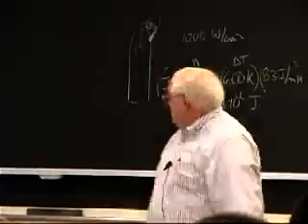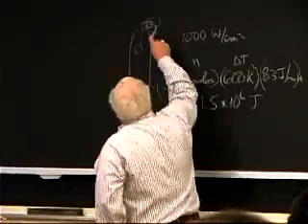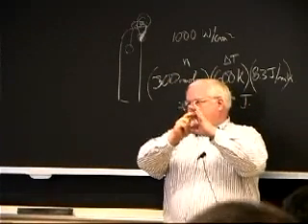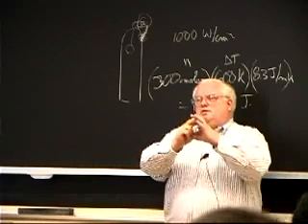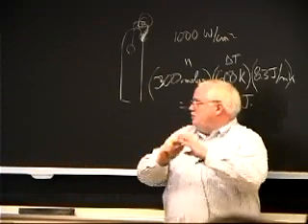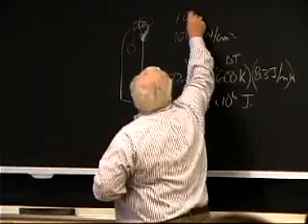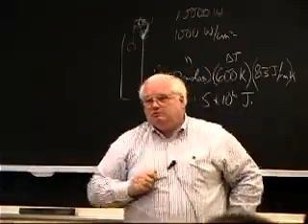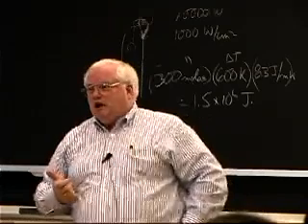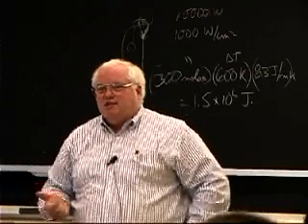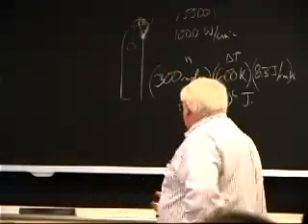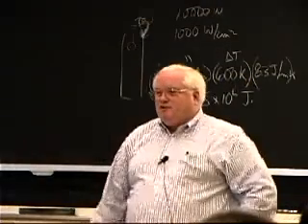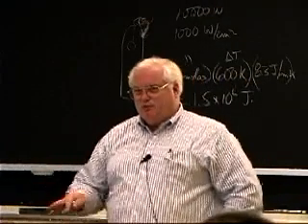Okay, and let's say I have a big flame here. It's not just one square centimeter. Let's say I have something that's about 2.5 inches in diameter. That's about 10 square centimeters. So instead of 1,000, I got 10,000 watts going into that tank wall. 10,000 watts over 2 seconds? How many joules is that? 20,000 joules. I don't think they quite made it, did they? So it's pretty easy to show that the external theory is bogus.